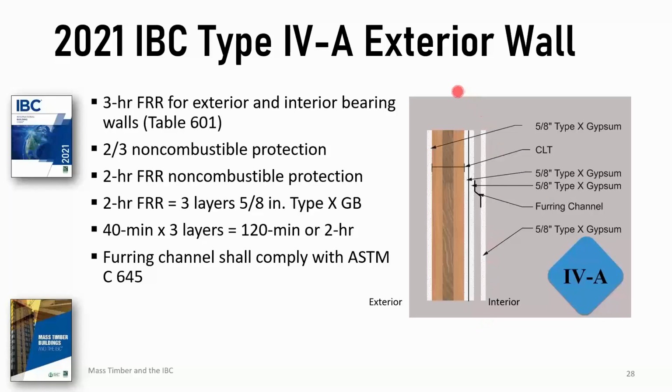And by the way, fire resistance for a mass timber wall that's solid timber is really quite different than a repetitive member assembly. When we did our first compartment fire tests with mass timber, AWC did it back in 2015. We did an exterior wall test and it was a 5-ply exterior wall. This just shows 3-ply.